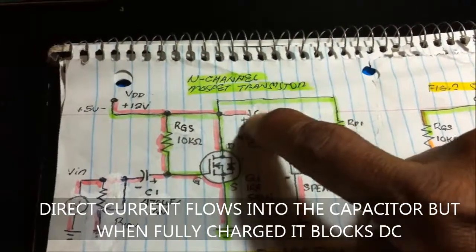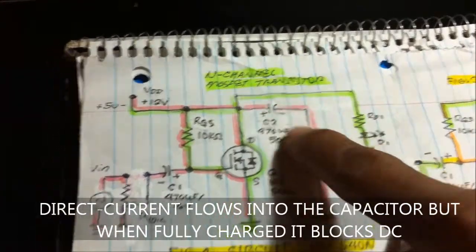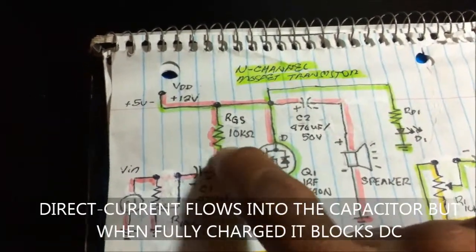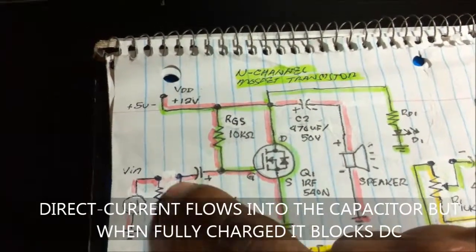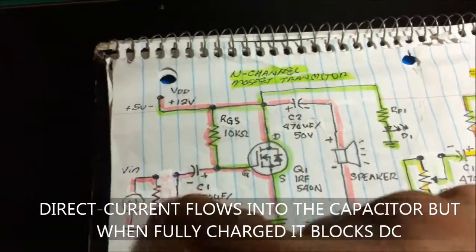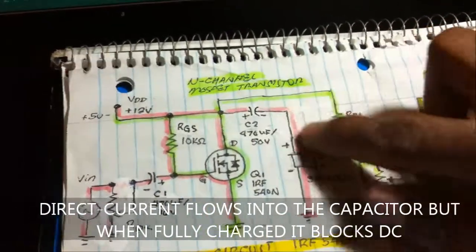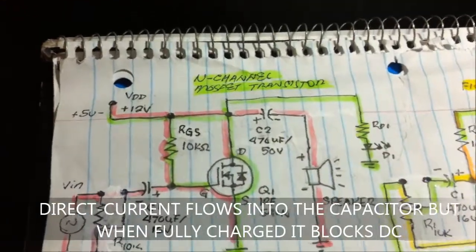Just like an open circuit here, open line. Also the same here in the input. Once the DC flows here, the capacitor will now charge, and once fully charged, it will completely block the DC. So it will not affect this input source and also the output source when we are dealing with DC.